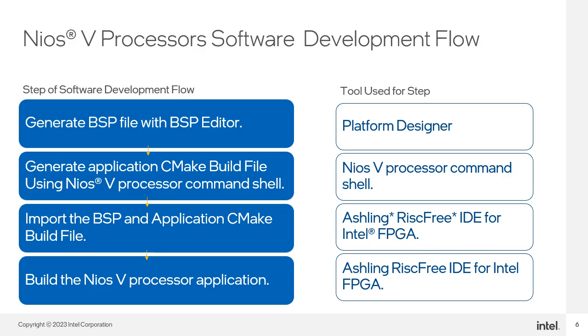You can program your FPGA with the SOF file produced from the hardware flow in order to use the Nios V application and debug in Ashling RiscFree IDE for Intel FPGAs. We will go through the tools described on each step in the upcoming parts of the training.